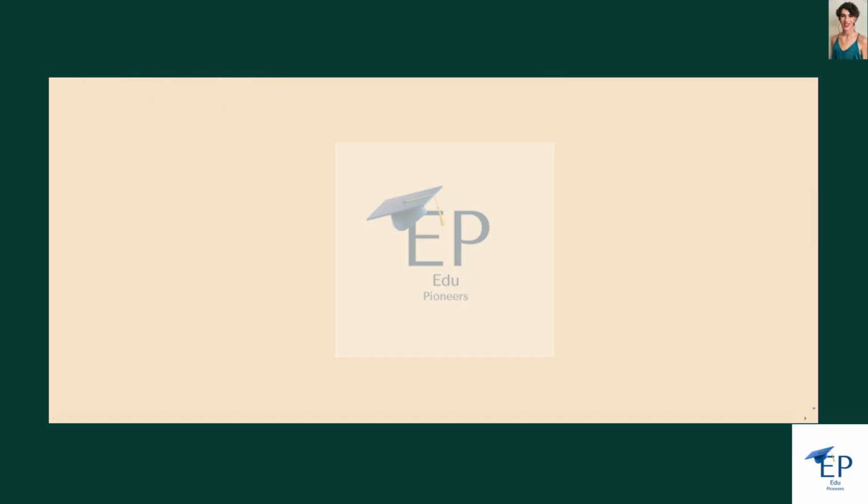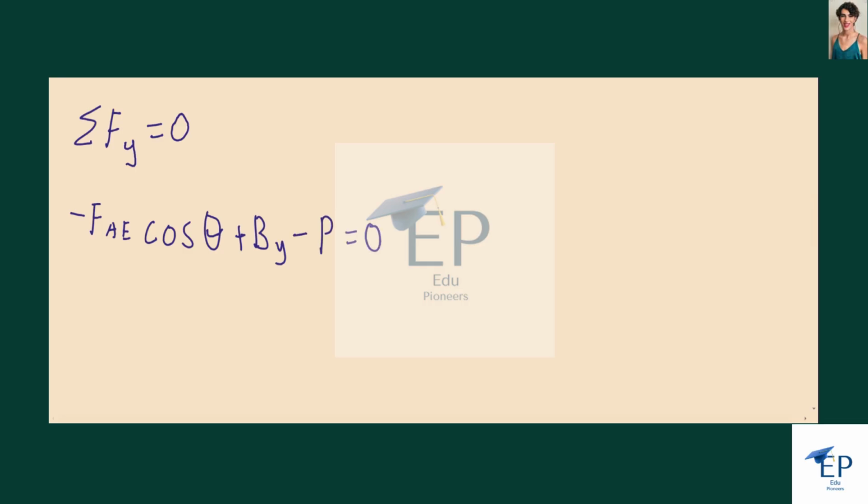So we now do the same thing for the y direction. So we have the sum of forces in the y direction is equal to 0. And we can write this equation as negative F of AE times the cosine of theta plus B of y minus P is equal to 0.